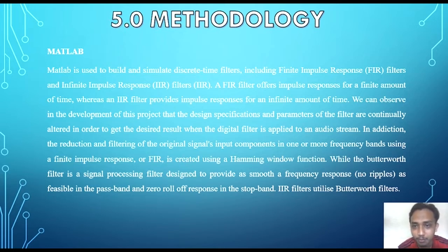FIR filters offer an impulse response for a finite amount of time, whereas IIR filters provide an impulse response for an infinite amount of time. We can observe in the development of this project that the design specification and the parameters of the filter are continually altered in order to get the desired result when the digital filter is applied to an audio stream.